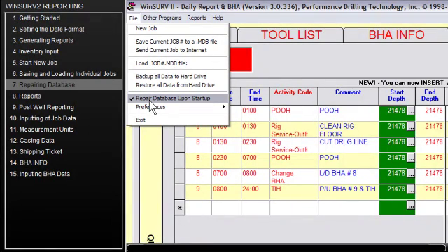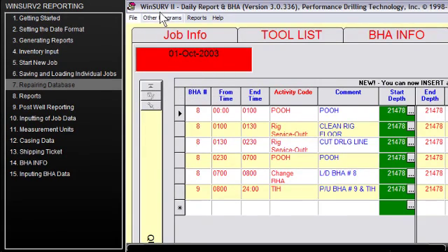If you're in the office and you have this checked and you have a lot of data on your computer and your database, then you may want to uncheck this and only check it when you begin to have certain types of problems. And it'll repair it and then uncheck it again. The reason being that repairing the database every time you start it is kind of unnecessary, but it can be very time consuming. And in order for you to save an amount of time, go ahead and just turn that off.